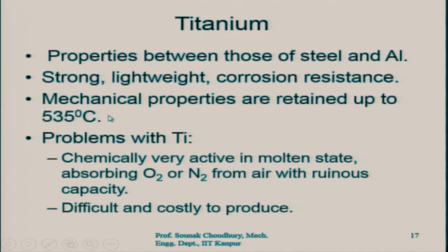So, the hot hardness is reasonably high. I would not say that this is very high, because 535 degrees centigrade is not such a high temperature, but still at this temperature the properties including the hardness are retained for titanium parts, for which the titanium material is widely used in engineering.